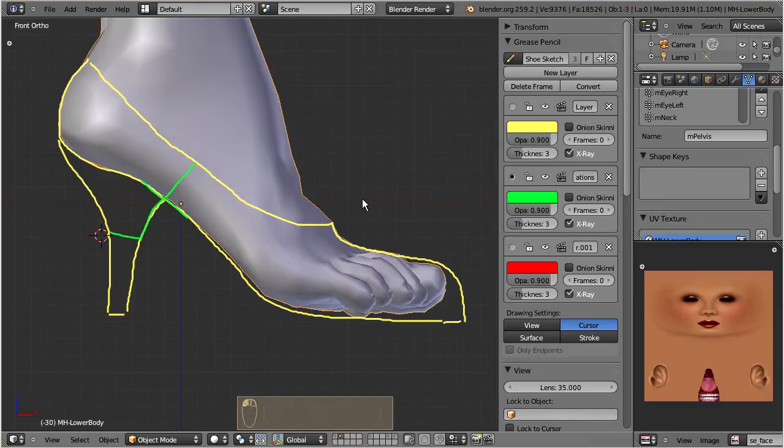The front part of the shoe may give us some trouble. Right now we do not exactly see what is going on here. But I am sure that we want our face flow follow smoothly along the sides, so I am almost sure that we will split up the mesh here, and we will create the top side of the shoe front by using some extra faces.